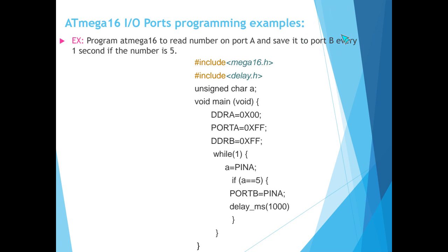For configuring a port as output, again we use the DDR register, DDRB. But now for port B, we want to configure it as output. Then for configuring it as output, we should write all the bits equal with logic 1.